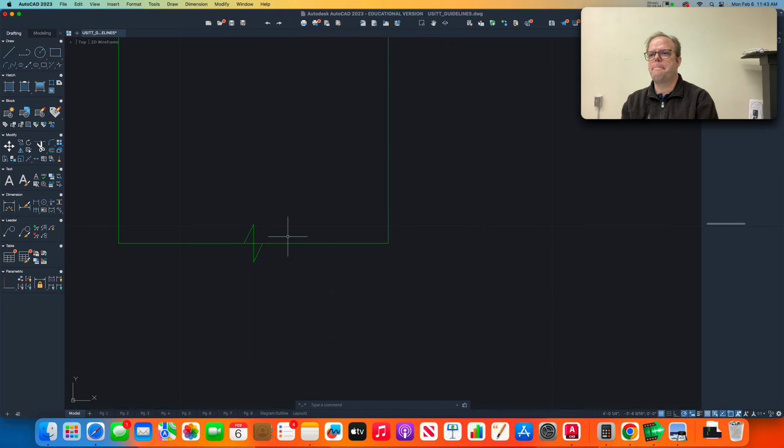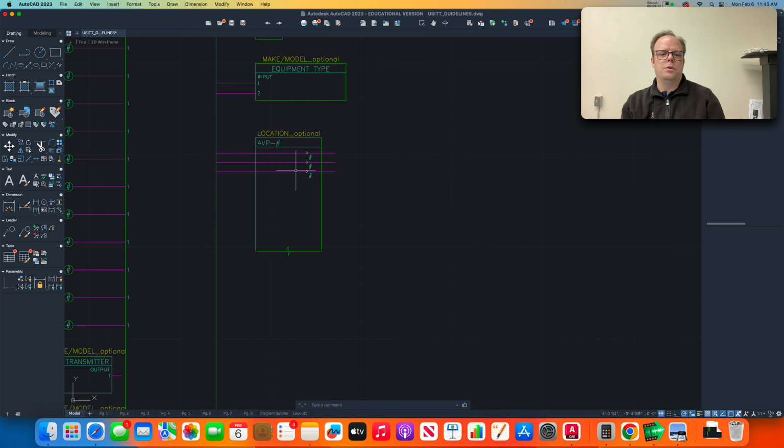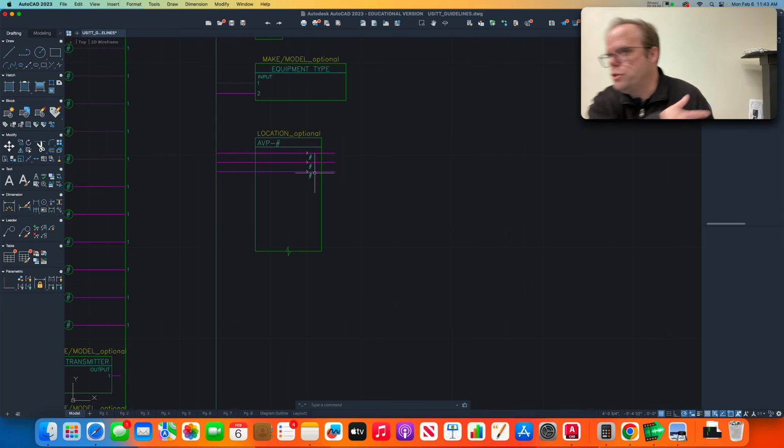You need help? How did you extend the line for the? So you type extend, enter, and then do B, enter for boundary edge, and then click on that right line of that big box for the boundary edge. Then hit enter, and then you just click on the 3 red lines, and they'll jump over there. You gotta make the lines bigger first. I was still trying to figure that out.